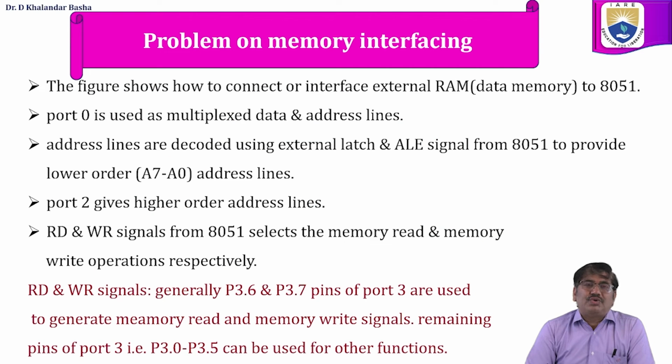So the figure shows how to interface the external RAM, which is a data memory, to the 8051 microcontroller. Port 0 is used as multiplexed data and address lines, that is AD0 to AD7. The address is latched using an external latch and the ALE signal, address latch enable, from the 8051, which provides the lower order address lines A0 to A7. Port 2 gives the higher order address lines A8 to A15.